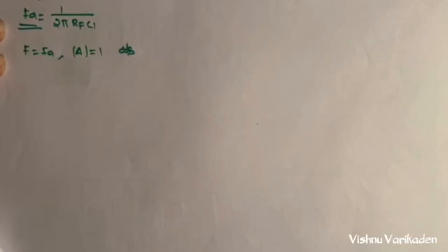These limitations of the ideal differentiator are overcome using the practical differentiator, with an additional component R1 connected in series with the capacitor C1, and another component Cf in parallel with the Rf resistor.